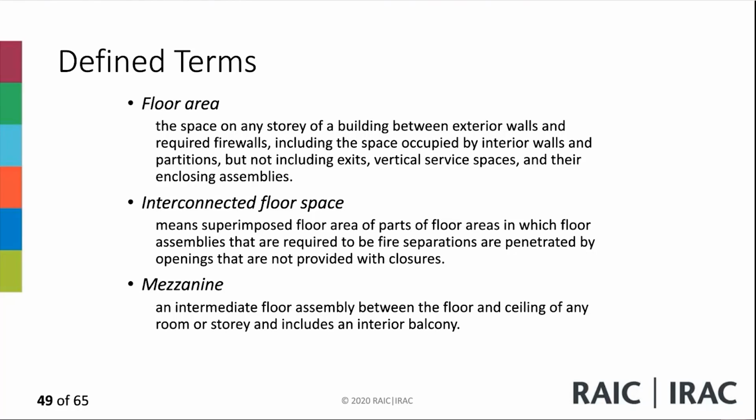So that means I can have different rooms, mezzanines, and as long as the mezzanine is an open area and it's got guards not higher than 1.07 m, then I do not consider them as a story, as long as within each room they don't take up more than 40% of that room area.